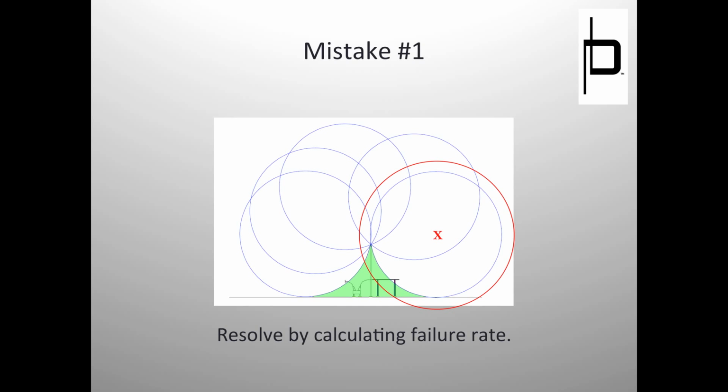So when you say 1 in 400 years or 1 in 500 years, what we're saying is the exposed area will get struck 1 in 400 years or 1 in 500 years. But for the quote-unquote protected area, we don't know how often that's going to get struck. According to this method, it's not going to get struck at all, but we know that's not true. It may have insulation failure, or for whatever reason, the step leader chooses to strike the equipment instead of the more attractive shielding electrode. Maybe you have bad grounding in the area, and that grounded shielding electrode is not that attractive. A number of different reasons. So when somebody says 1 every 100 years or 1 every 400 years, they're referring only to this exposed area.